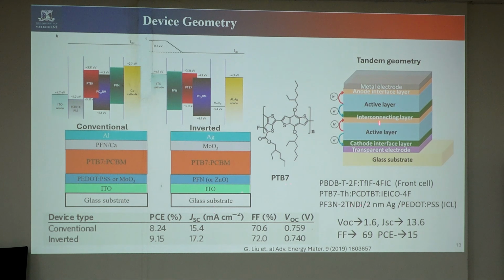But when you add this stack, the voltage will get added up. Suppose this is giving 0.8 volt; when you connect this stack layer, the voltage will add up and we will get 1.6 volt, so that we can get enhanced efficiency. When you have a series device, same as in any series circuit, the voltage will add up, but the current will be the same. So the problem here is that both active layers should generate equal current. If different currents are generated, because of the current mismatch, it may only take the lower current.